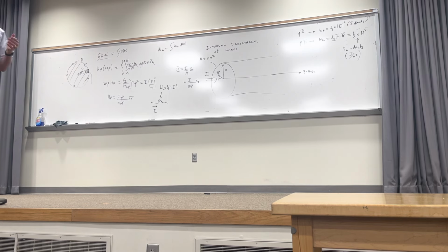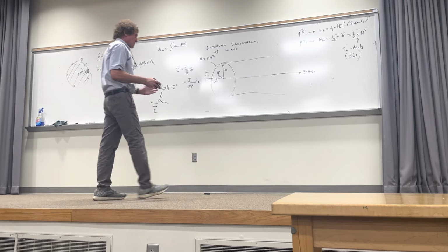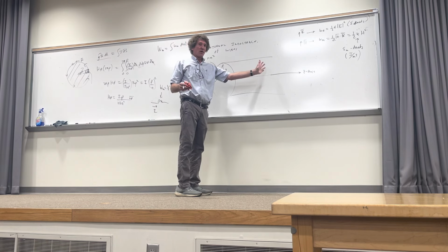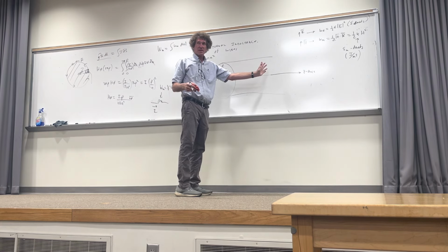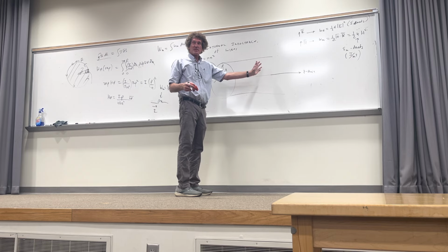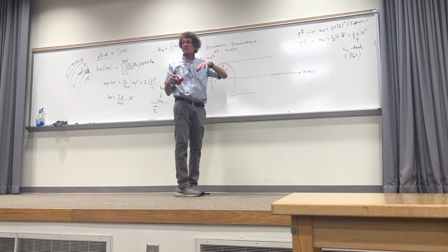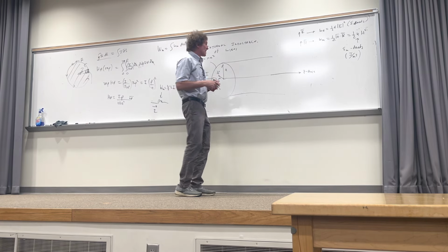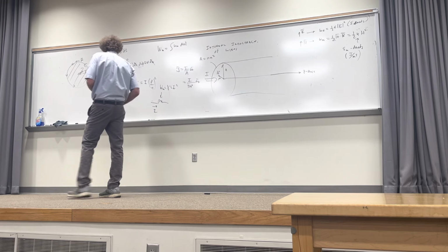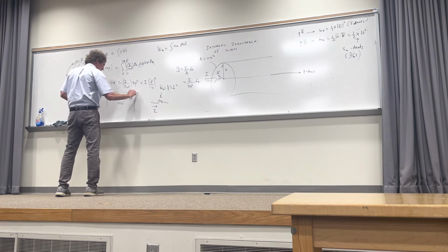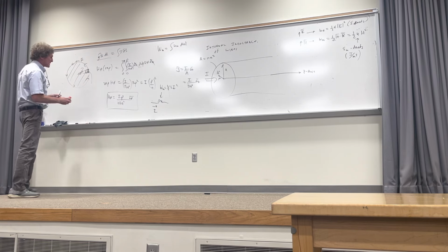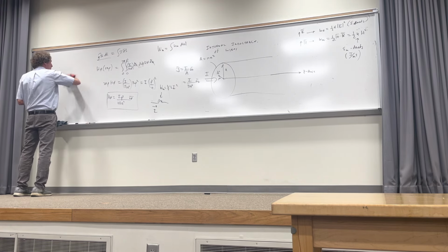So now we equate these things. We're going to say that the total magnetic energy inside the wire over some length, say 1 meter, has to be the 1/2 L I squared, L being the internal inductance per meter, and that will be equal to the integral of the energy density over that region. Does this make logical sense then? All right, so now I'm going to have to do that over here. Remember, this is my H field. So I've got that, and I think I can do it right here. This shouldn't be very hard.